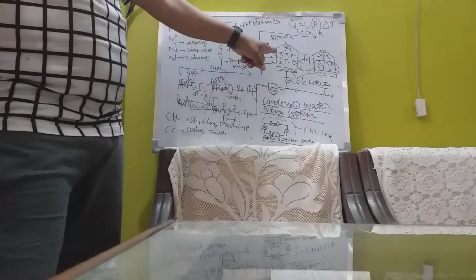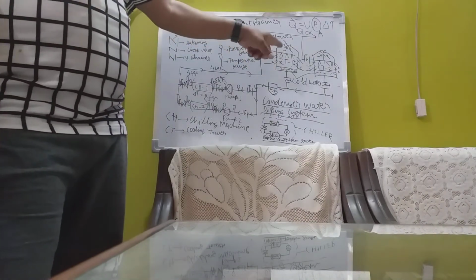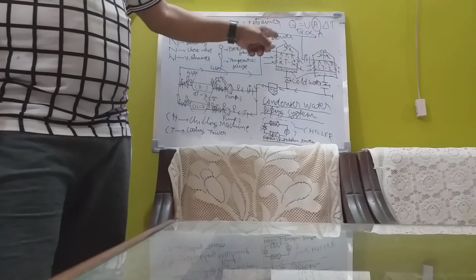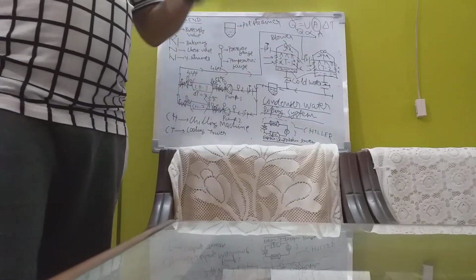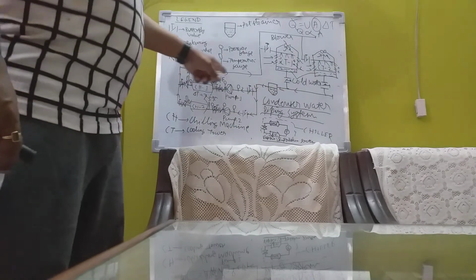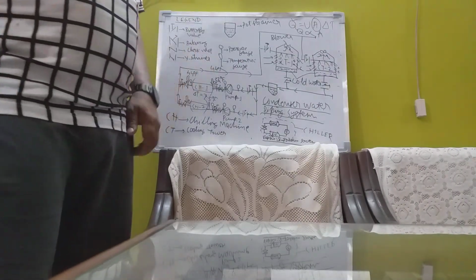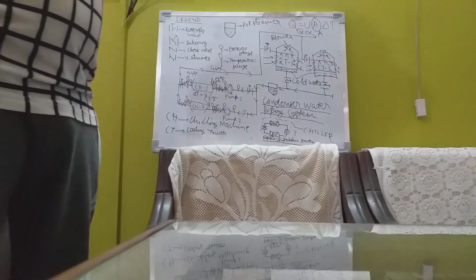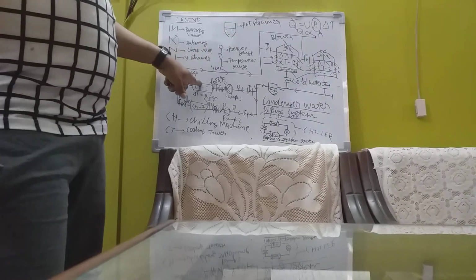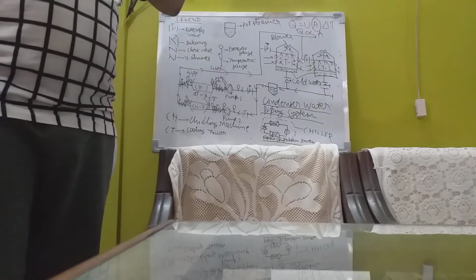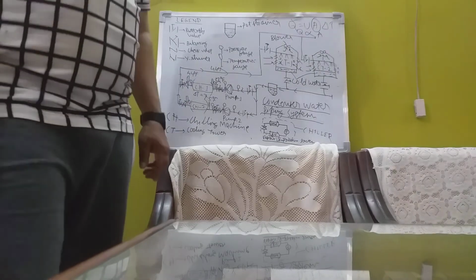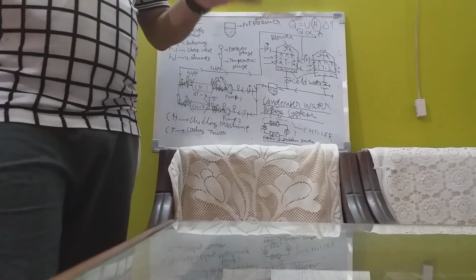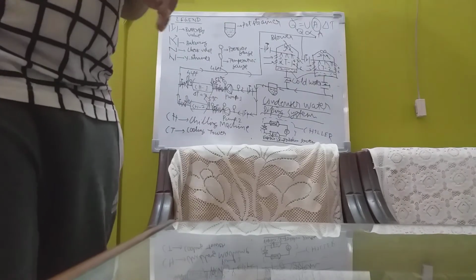They are not using the water cooled system. This is called water cooled system because you are cooling water through a cooling tower. Water means condenser water. In case of Gulf countries, instead of a water system, they are generally using air cooling in chilling machines. That means the condenser is cooled with the help of air, as it is done in case of your house air conditioners. The air conditioner in the house is a small capacity air conditioner, we can cool